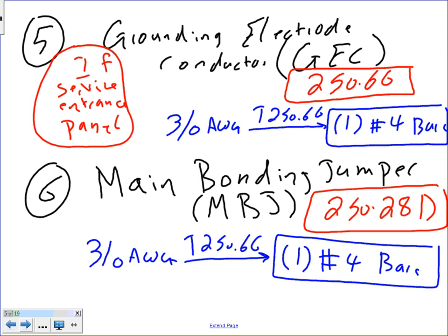That's the one that you tie the neutral to the ground. They call it grounding the neutral. That's the one that we ground the neutral with. It's called the main bonding jumper, per code 250.28(D). And that will get you the main bonding jumper, guys. If these conductors are more than 1100 kcmil, we have a different calculation that we're going to be using later on. Any question, guys?